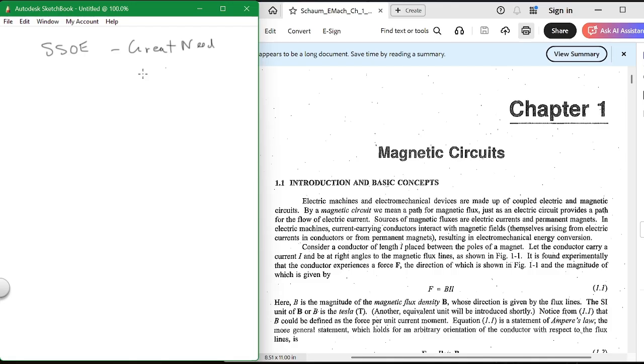In other words, bring your software in, show us how it works, show us how you do that. It's a load calculation type question, or there's a one-line drawing for your plant. It's called a one line, and it shows you where all the power goes, and how to figure all the numbers on a one line, that type of thing. The other thing is how to find the short circuit current rating of a panel, SCCR of a panel. Now that may be easier, but I want you, when you walk out of here, to know how to do that. Hopefully you will.